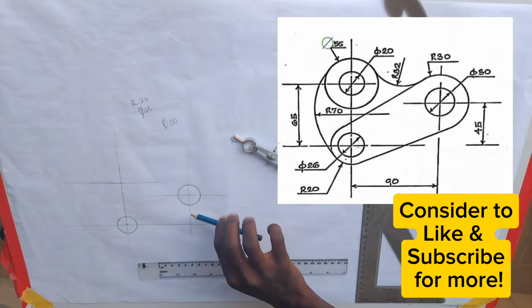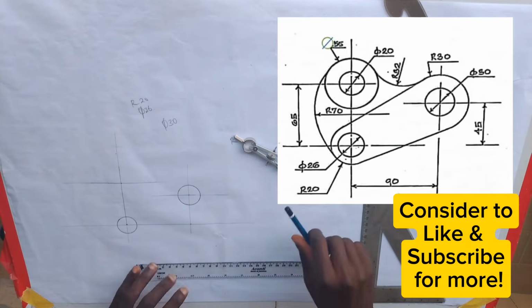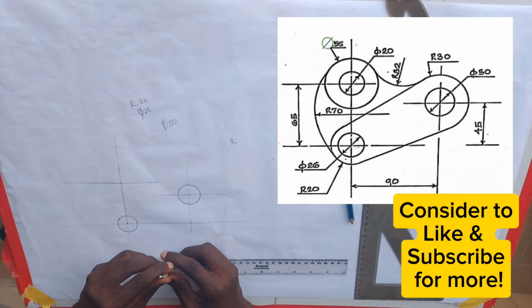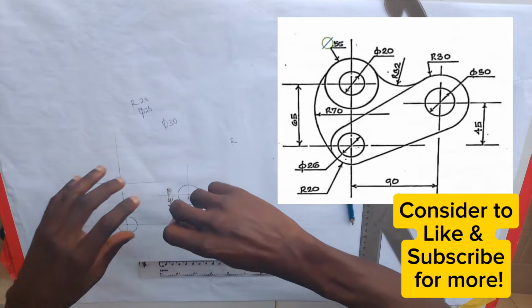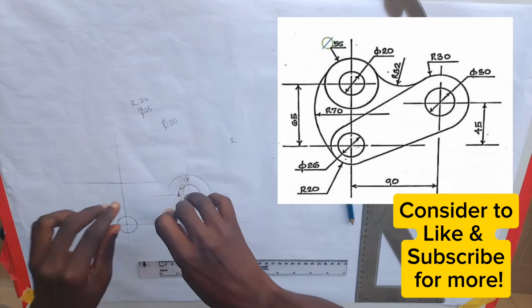So we need to know the radius of the arc. Now for this side, you see that the arc here has a radius of 30 millimeter. So that is 3 centimeter. So I'll measure 3 centimeter. I hope you know how to convert from millimeter to centimeter. If you are converting from millimeter to centimeter, you divide by 10. So when we have 30 divided by 10, that will be 3 centimeter. So I will make an arc here.